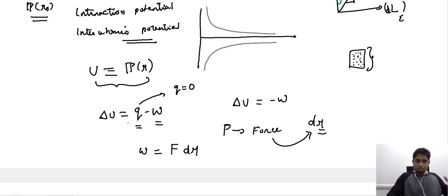So we start by talking about the internal energy of the system based on the interatomic potential energy. Now we impose a uniaxial tensile load, and there is a corresponding change in the internal energy. In order to quantify this change, we bring the first law of thermodynamics into play. We assume that the role of thermal energy is zero, so the first law reduces to this expression here.